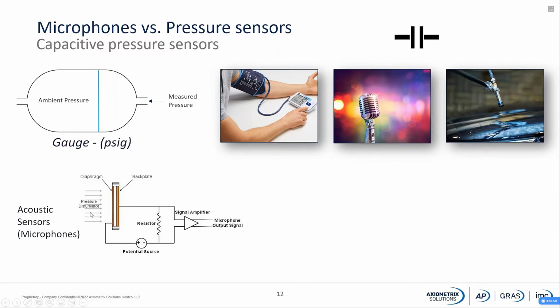So you basically use it as a capacitor, and then you let the sound wave push on this one, and you get the signal out on the other side. This is a little bit more schematic picture, and there you can see a house, the backplate, an isolator, so there is no electrical connection between, and the membrane on top here. And then you see a small air gap in between. So this air gap is changing, and therefore you get a signal on the microphone.